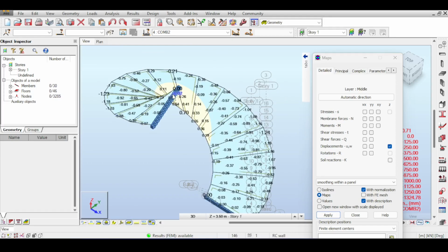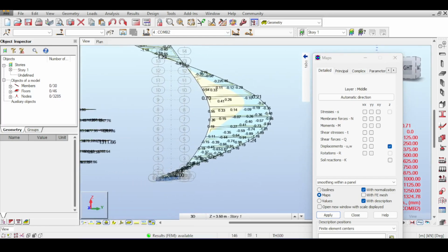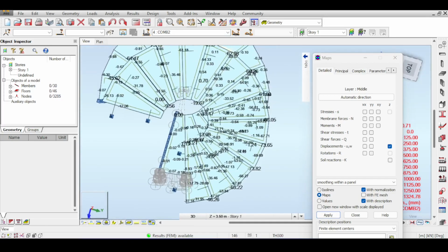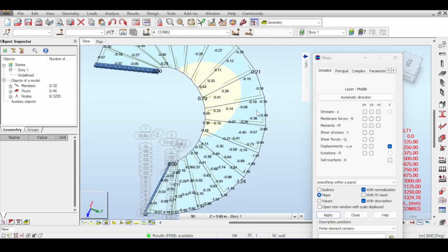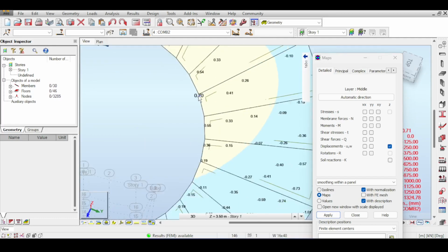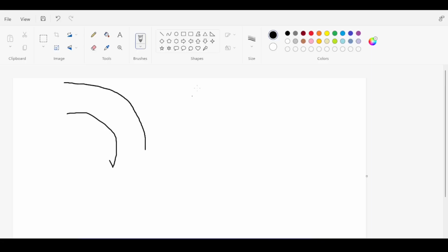Of course, what are the things that affect the deflection? The first thing that affects the deflection is, of course, your staircase length. The second thing that affects the deflection is your external diameter. The external diameter of the staircase is what is going to deflect the most. The internal diameter might even deflect upwards, and this is what happened here. This one deflects upwards. As strange as it sounds, it deflects upwards because you have a twisting effect, a torsion effect here, which will push this point down and take this point up. It's totally normal and to be expected. This is nothing new and nothing strange.